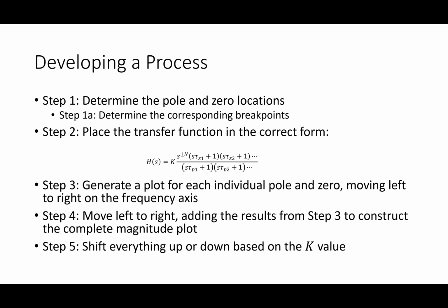And then what you're going to do is determine the corresponding breakpoints, which are always going to be positive. It's going to be the frequencies. We only look at positive frequencies. So we basically say what's going to happen at those frequencies. Those breakpoints, we call them that because what does the graph do? It breaks at those points. In other words, it's flat and then it rises, or it's constant and then it falls, or whatever, right? Or it changes its slope potentially.